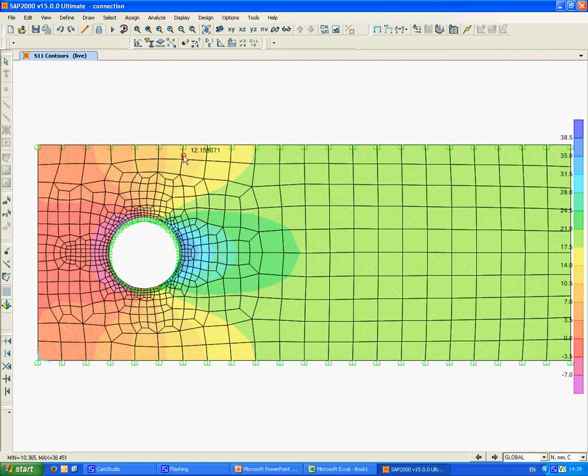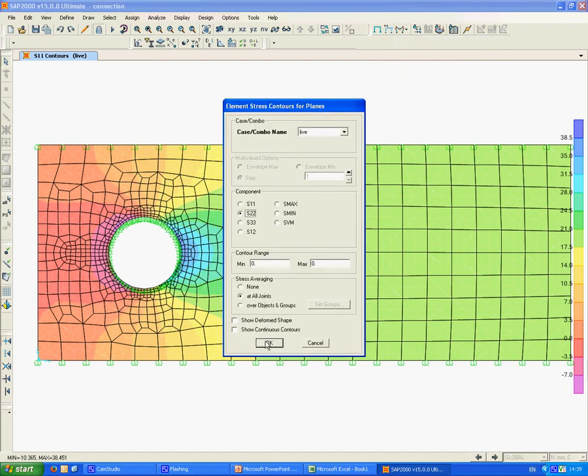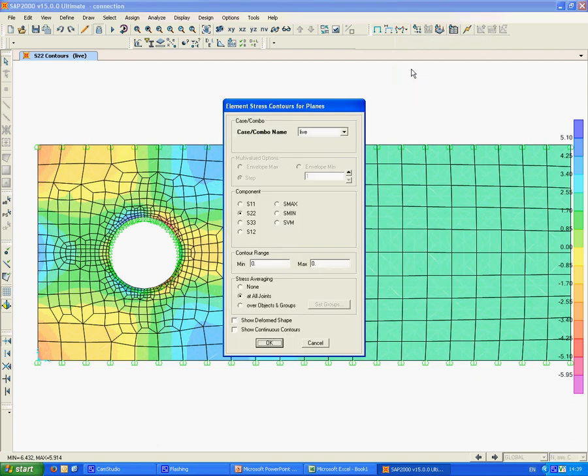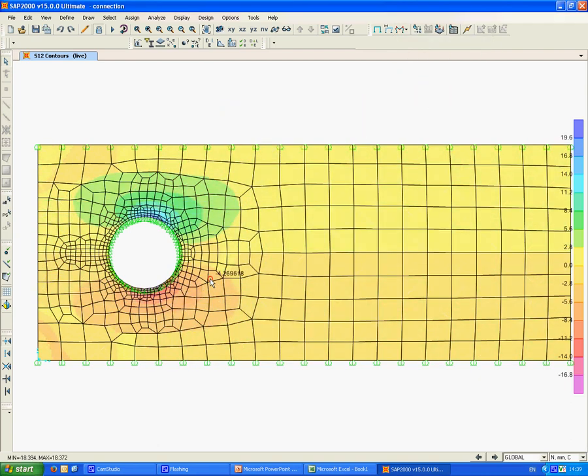So if you make a cut around this section here and you calculate the integral of the stresses, it should give you 60 kilonewtons, but of course the distribution here follows a different pattern than here, so you have a peak value here, a lower value there, and almost constant distribution on this area. You can also plot the stresses in the vertical direction. You can also plot the shear stresses, which are also quite important, and you see a large concentration of shear stresses around these two areas.